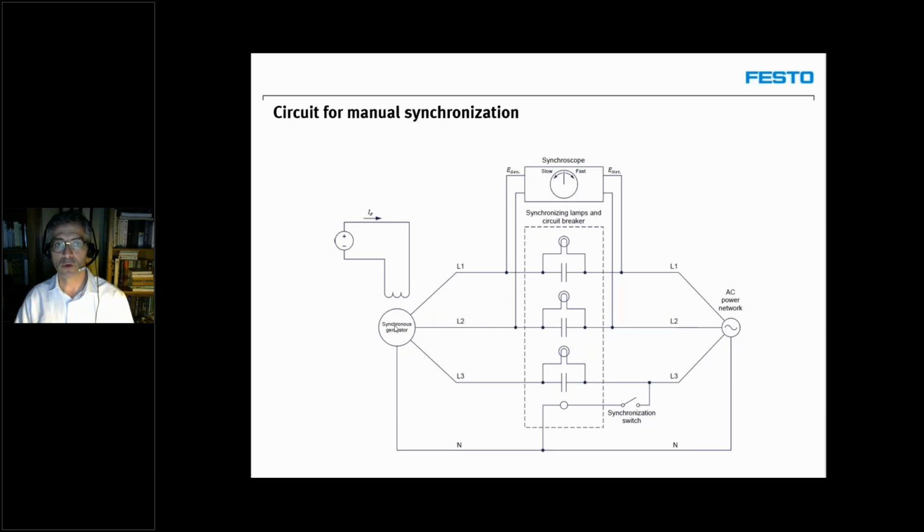So we will be able to monitor the voltages on both sides, make sure that they have the same frequency, the same sequence, the same voltage amplitude. And once all these conditions are met, we will close the switch to connect them electrically.